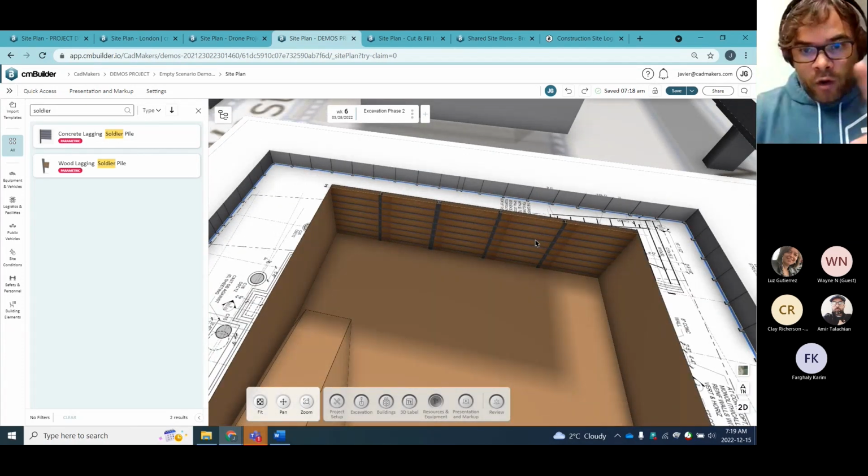The customer modeled both options, soil anchors with shotcrete wall versus the raker system, analyzed the schedule, visualized it with CM Builder, and showed the client, hey, it's going to be a 5 to 6 month hit to the schedule. How much is the owner asking for the underpinning? It's $2 million. Okay, well, if it's $2 million, maybe just pay the owner instead of taking the schedule hit, right?